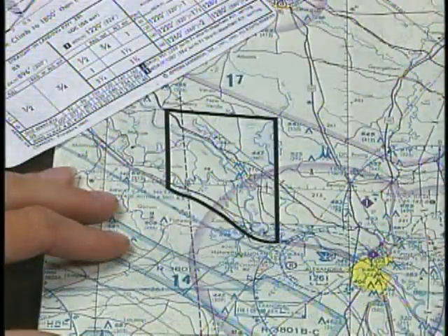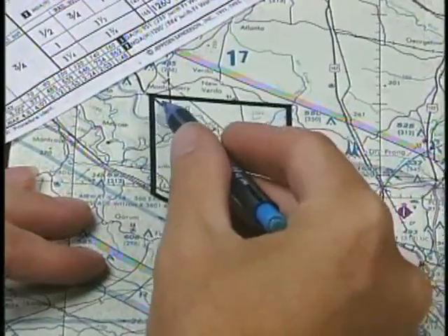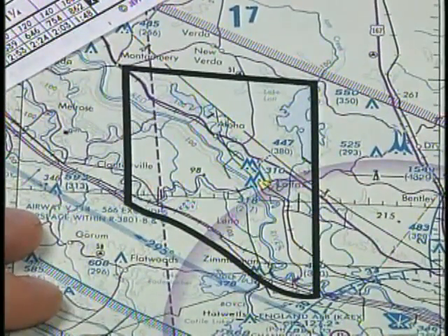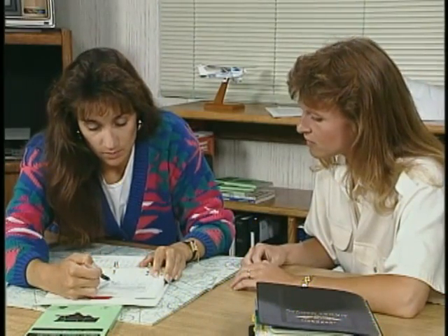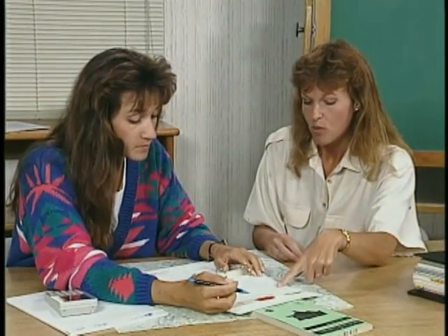The pilot may want to begin training for an additional rating or feel the need to review specific subjects or maneuvers. In addition, it may be necessary to point out local practice areas or the availability of practice instrument approaches if the pilot is a flight instructor. In preparation for the flight, it is important to explain how the area's climate and elevation will affect the airplane's performance. The pilot should calculate performance for the airplane based on local conditions. This is necessary regardless of the area.